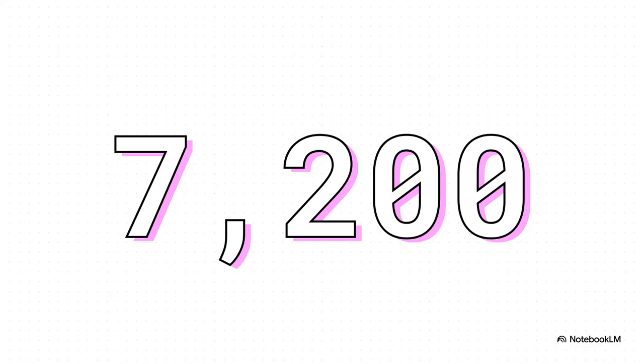And what happens when you get a lot of that friction, a lot of resistance? You get heat. And I mean a lot of it. This calculation from question 7 is wild. A 500 ohm resistor with just 1 amp of current, in 1 minute, it generates 7,200 calories of heat. But see, this isn't a problem. It's a feature. It's exactly how your toaster toasts or how an electric stove cooks your food. It's just turning electrical resistance into useful heat.